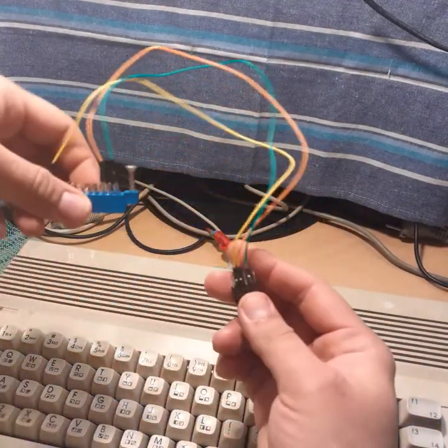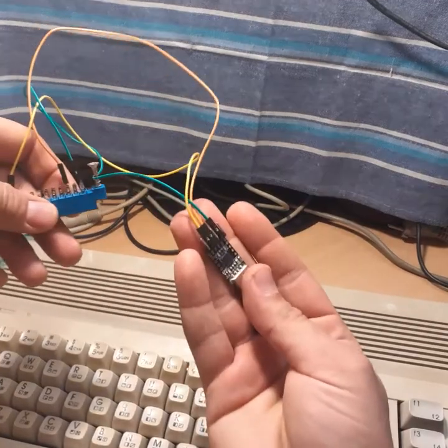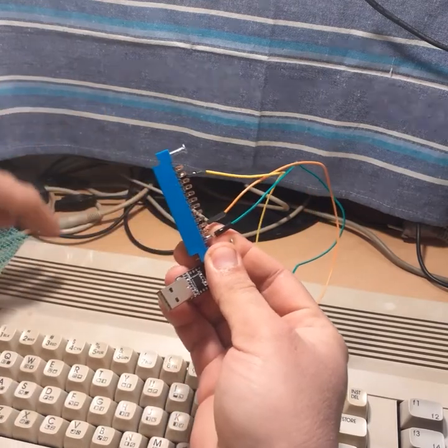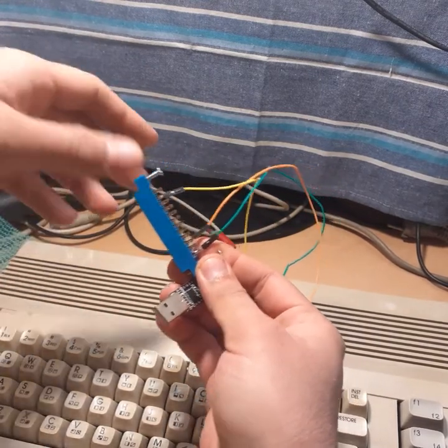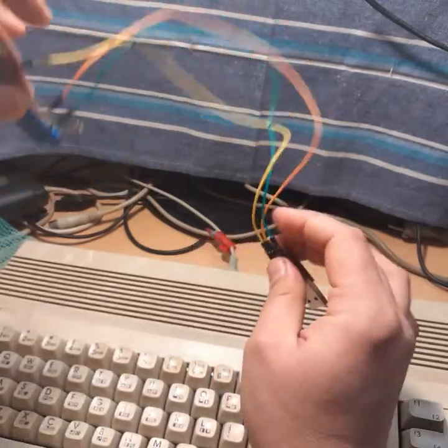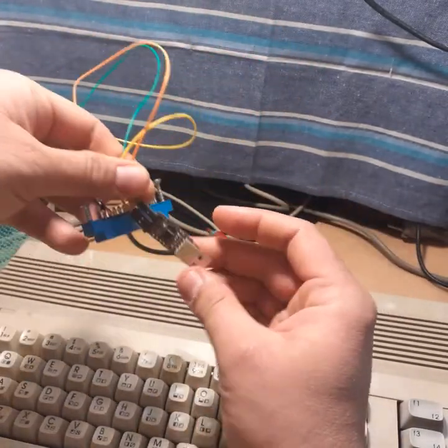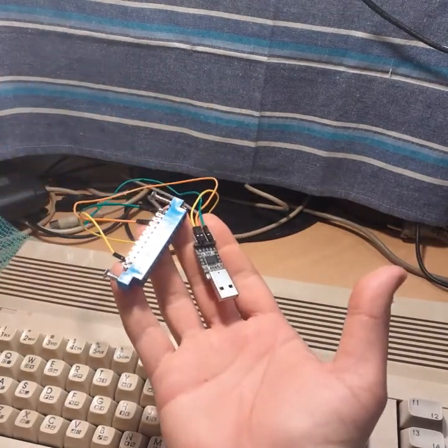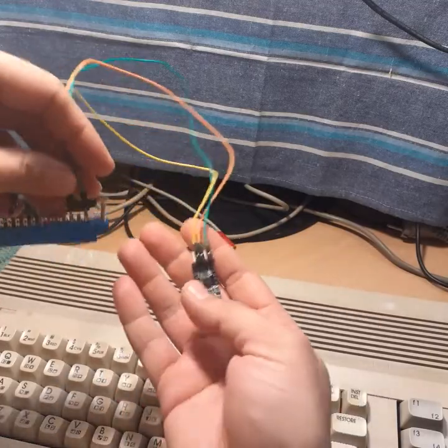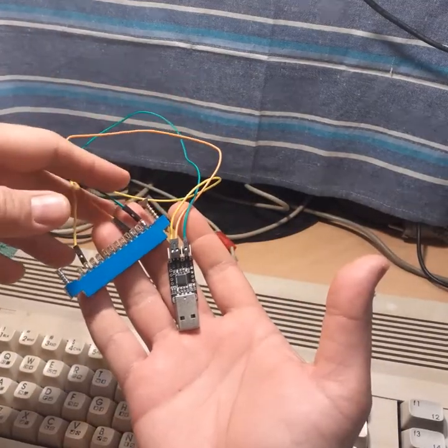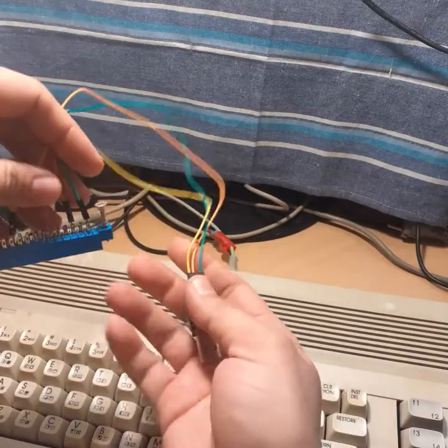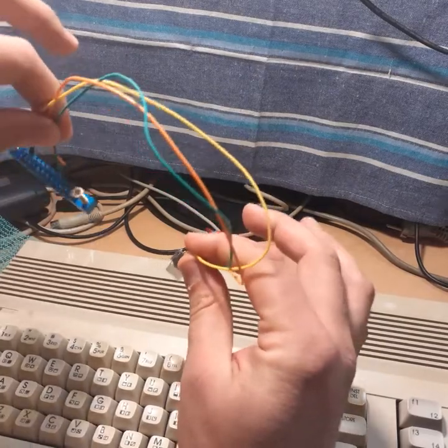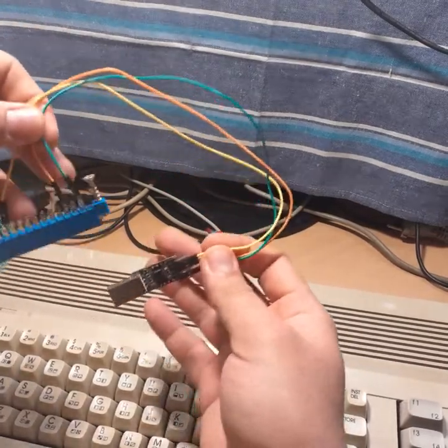Now I already wired a USB to TTL converter to an edge connector that connects to the UserPort on Commodore 64. We use just 3 wires, so it's that simple, and we are ready to do some testing. Now, before that, all these schematics will be available in the video description. And before we do any testing, let's check how two devices communicate via serial protocol.